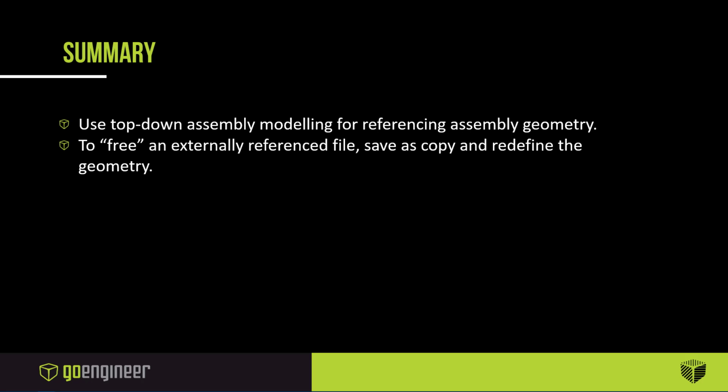Also, if you break an external reference, you cannot get rid of that icon in the feature tree there. So if that matters to you, you may want to make sure that the external reference never gets created in the first place when you're modeling. So that icon next to your part name might be a consideration for how you choose to handle those external references or when you want to break them.